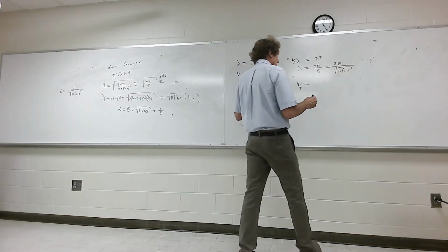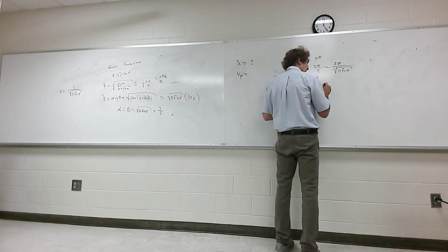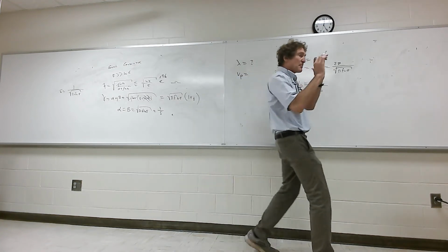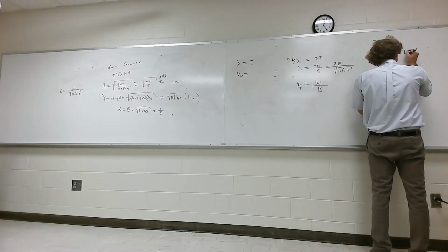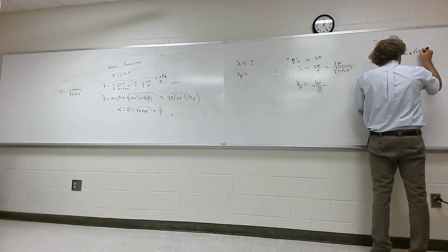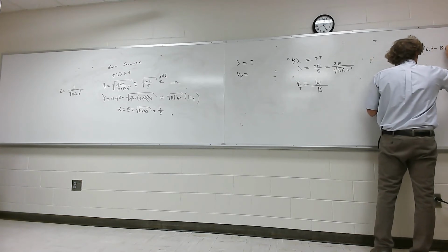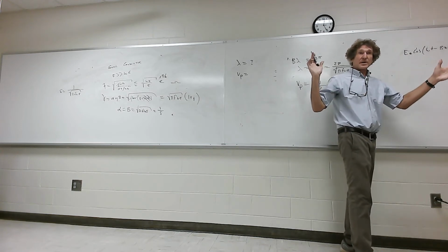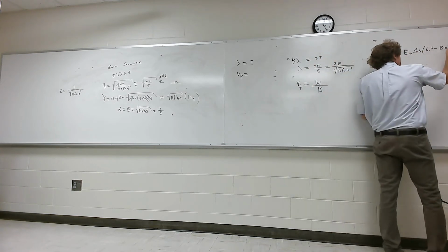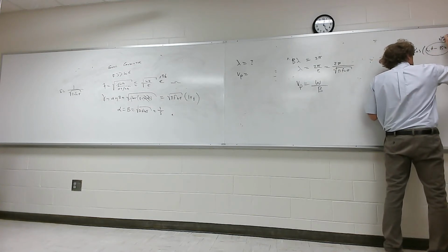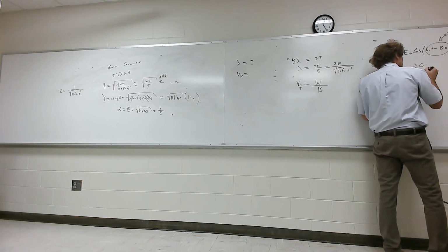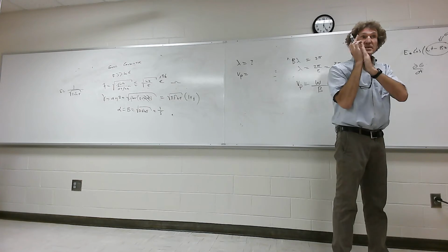Well, y'all remember it's omega divided by beta. You remember where I got that? Just to refresh your memories. Remember in the equations for the electromagnetic propagation, you get this kind of effect times cosine of omega t minus beta z ax. I'm just writing this down to refresh your memory. Y'all remember that's the general form of the time domain, right? The argument of this is an angle. And if you take the derivative of the phase with respect to time, you don't want that to change. That is the phase velocity.